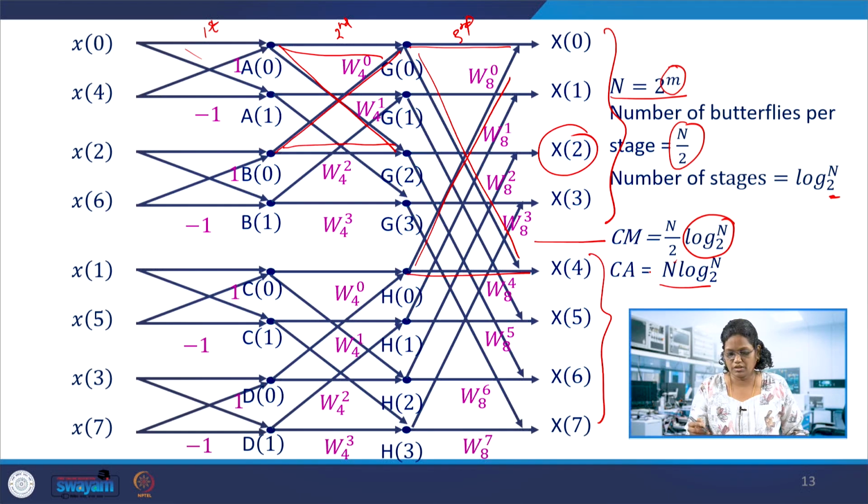In the DFT we calculate all the k values, and the FFT also gives all the k values, but in the STFT we compute for one particular index, either k equal to 1 or k equal to 3, whichever frequency we are interested in. Similarly, we had looked into the variants MSTFT, HTFT and MHTFT. So if I don't want all these bins and only one is needed, then we can go for the STFT. But if you want all the coefficients, the FFT would be better. But if you want the instantaneous X of k1 and X of 2 or something, then it is better to use the STFT.